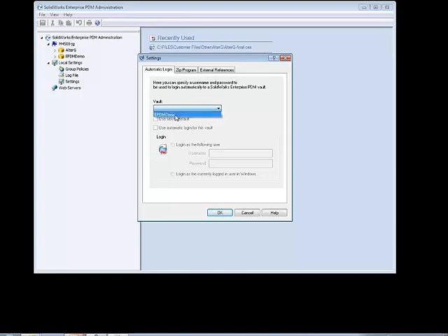First thing I do is select my vault view, and then if I wanted to force it to use or not use automatic logins, I can uncheck the box that says use server default, and I can specify here to use automatic logins for a particular vault.